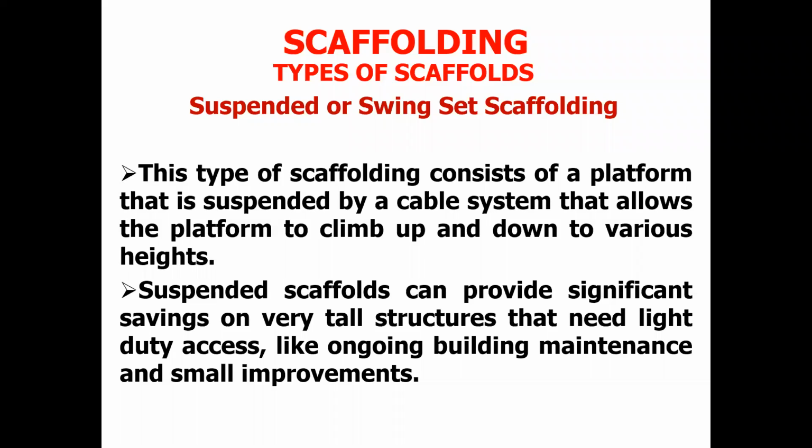What it simply means is that if you do that, the entire street, the entire activity in that place will come to a standstill just for you to be able to place a scaffold to do the cleaning at that height. So for that purpose, suspended or swing set scaffolding is what is used.